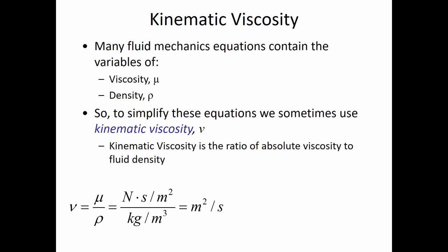variety of temperatures. And the units, if you see how the units cancel out, the dynamic viscosity is going to be newton seconds per meter squared. Of course, we already know that kilogram per cubic meter is the units for density. And since a newton is a kilogram meter per second squared, we're going to expand out that newton into its base units, where all units are essentially made up of mass, length, and time.